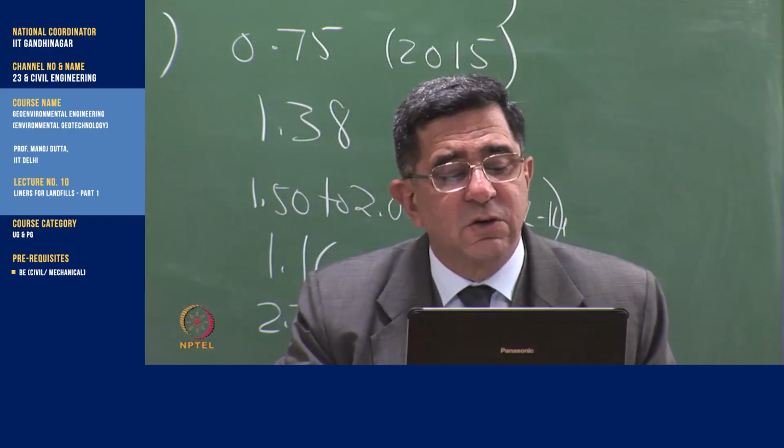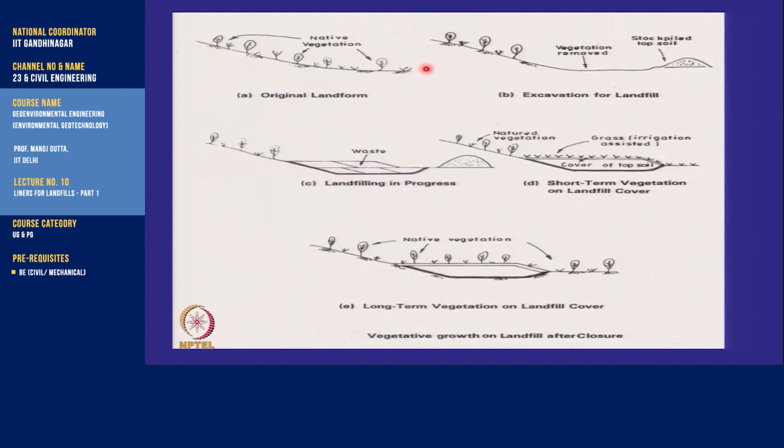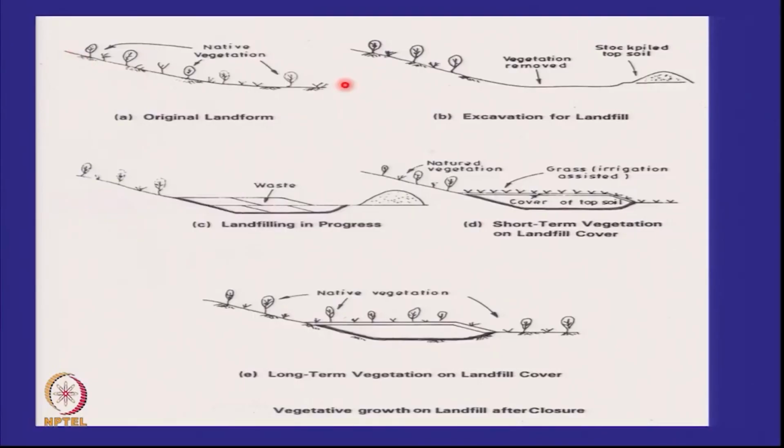So conceptually, this is what the broad picture of landfills is. We found a location which nobody was using for disposing our waste. We cleared it up, we put a liner, and we put our waste in daily cells, then yearly phases, and then when it was all over, we had a covered landfill.